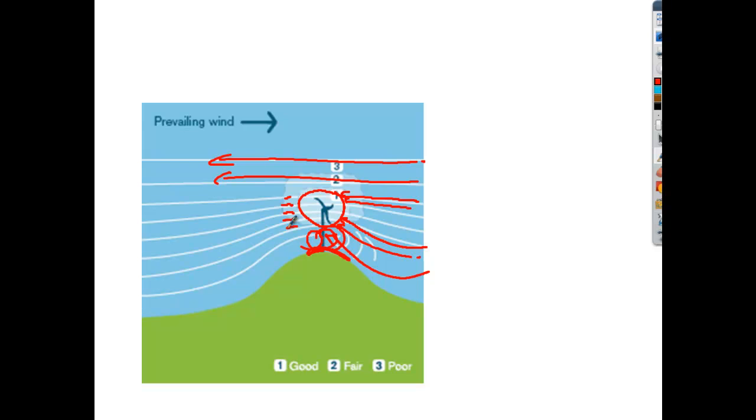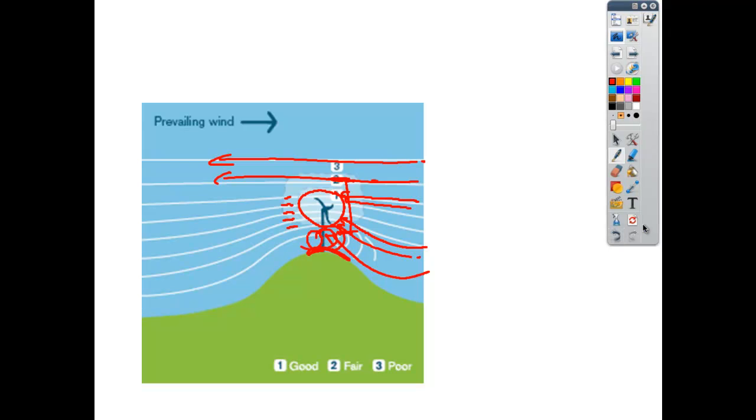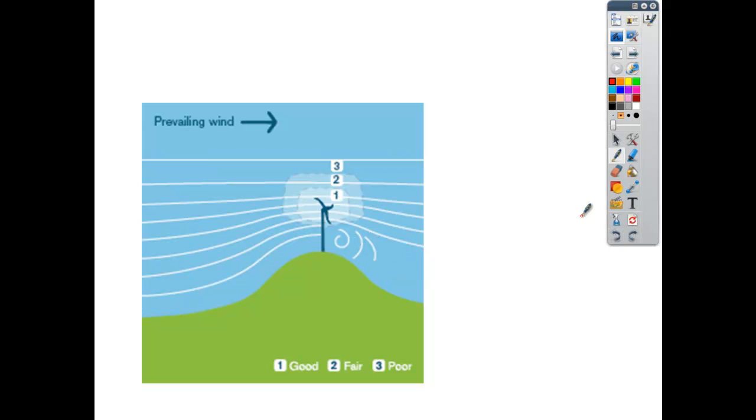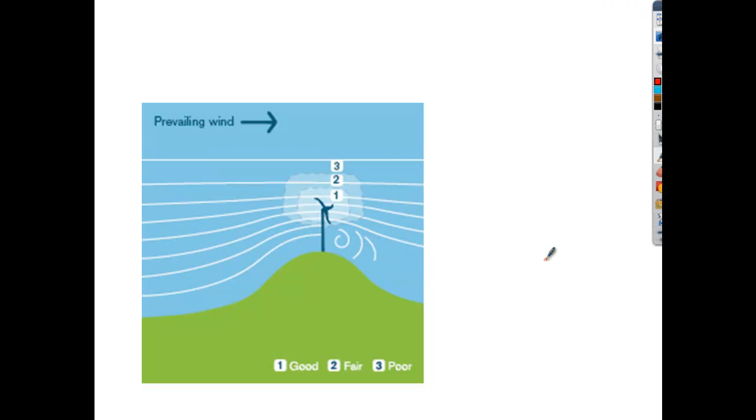Just as much water has to get through that then in a wide point. So the only way it could do that is by traveling faster. Well, the only way the wind can get through this point right here is by traveling faster. So you have a maximum wind speed right above the mountaintops, but not too high up, so you don't get that compression from the mountain. So you have a maximum or best location right here, where the winds are compressed and traveling fastest. And that's where you will see wind turbines placed.